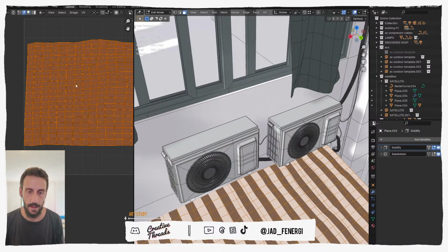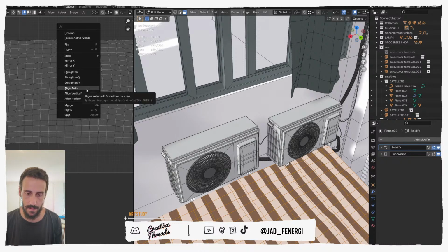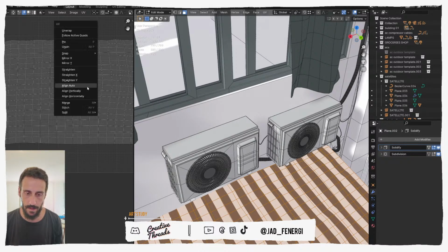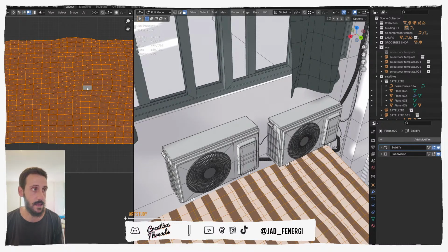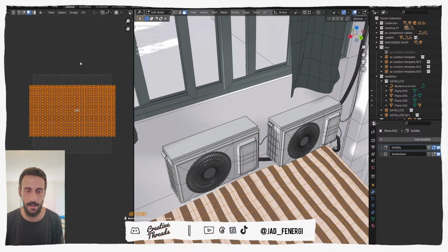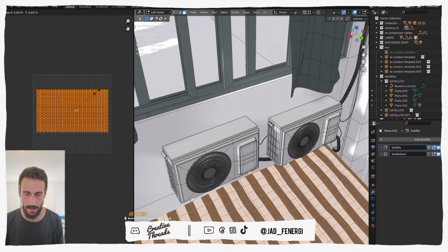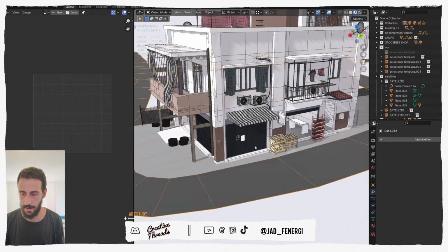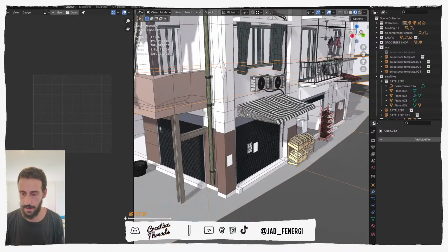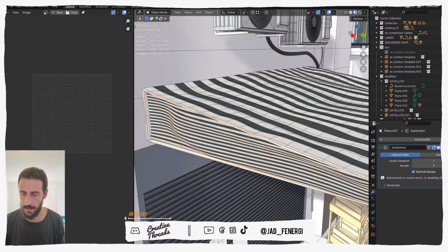And then let's also pick a face. It doesn't have to be in the middle, but it's just what we're doing. So align auto, faces, all the faces, double shift click on this, right click, and follow the active quad, and just scale it. And you can see now that these are following much better. Let's do it for this, guys. You can see it's too small.